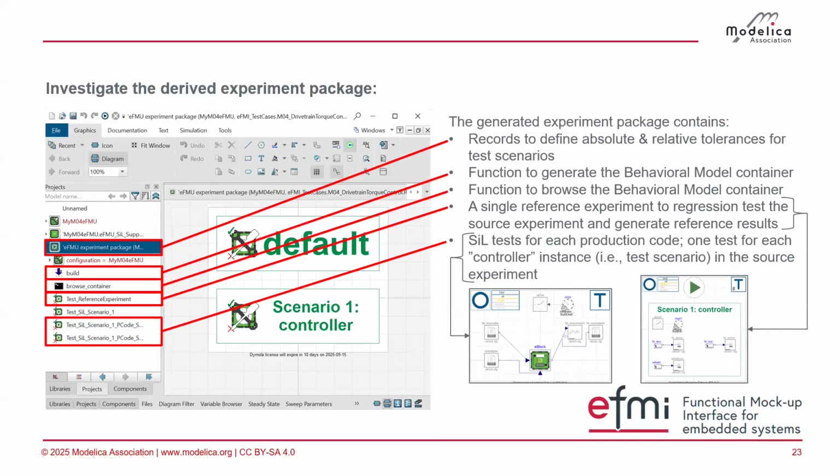If we would have more instances, there would be more scenarios because each instance describes the expected input-output behavior. Then we have the possibility to define tolerances. And tolerances may not be always the same for every scenario. So you could define for every scenario individually by double-clicking this little thing here, or you can define for all the scenarios at once using the default tolerances button. This is a way to define the tolerances.